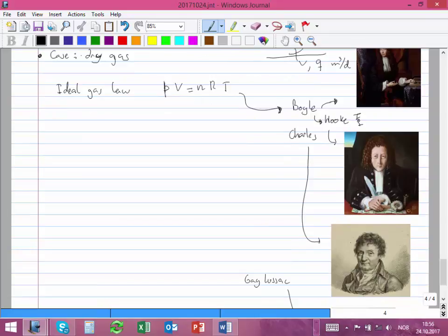But really, what people start looking at is, I have this general equation, and I start to use it on any substance that we have. But what people saw is that there was a deviation between the volume predicted by this equation and the actual volume measured. That deviation could go between 0.7 all the way to 2, a relatively big deviation. So they started to plot for each substance. What they did first was say, we're going to insert a correcting factor in the ideal gas equation.